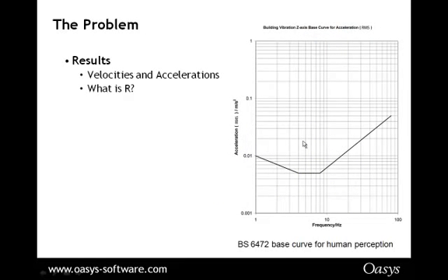And from these accelerations, we then get a thing called a response factor, which is a measure of human perception to vibration. You note that people are most sensitive in the range of about 4 to 8 hertz vibration, less sensitive for low vibration frequencies, and much less for higher vibration frequencies. Note people are more sensitive to horizontal vibrations, but that's another question.